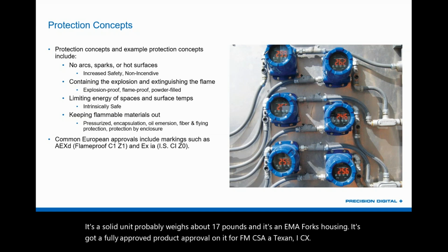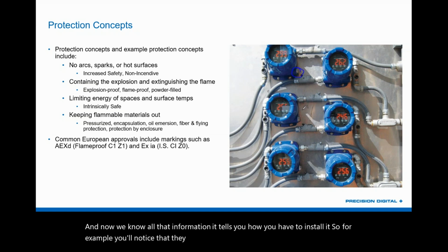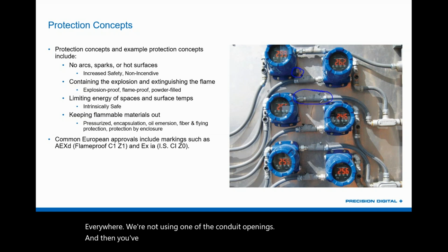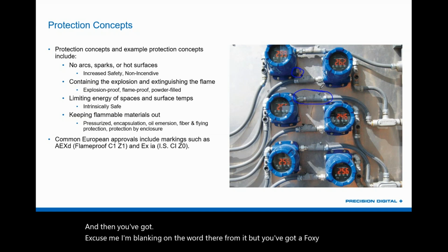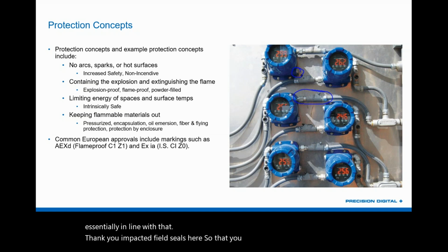And now that we know all that information, it tells you how you have to install it. So for example, you'll notice that they have approved plug installations everywhere where we're not using one of the conduit openings. And then you've got epoxy filled seals here, essentially in line with that, so that you can prevent the explosion from traveling down these lines.